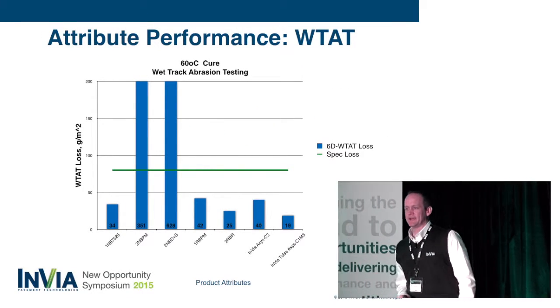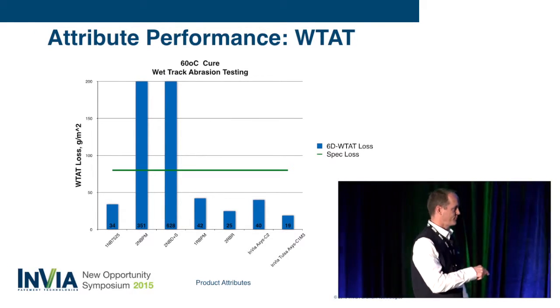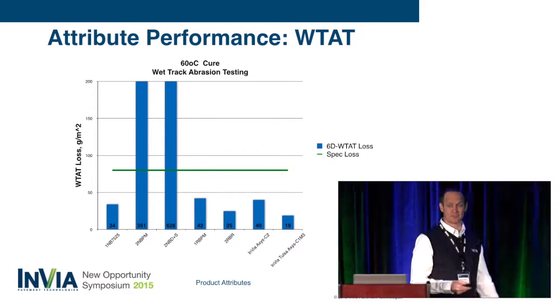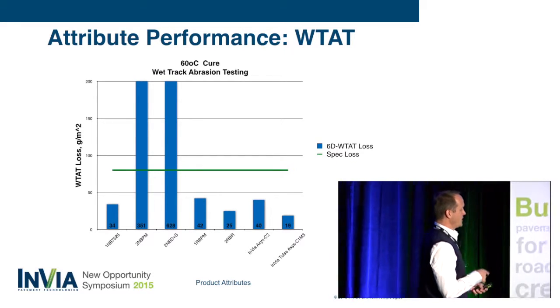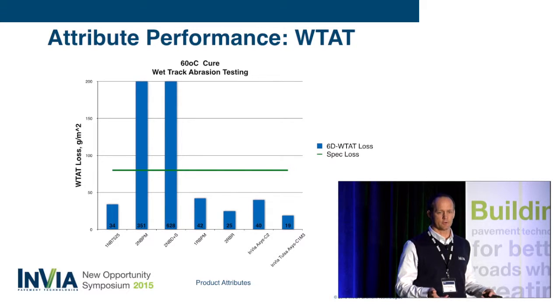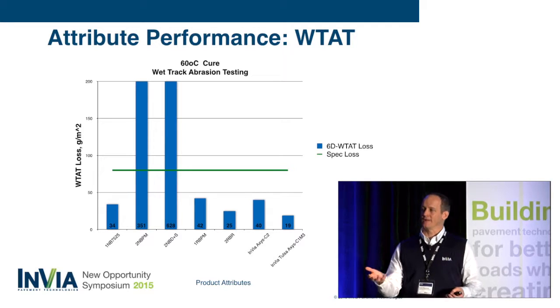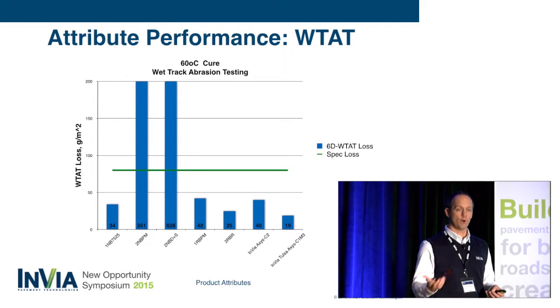I'm not sure if you guys paid attention to the second best performer in that dry time, but I thought I'd go ahead and share with you the wet track because that's our durability surrogate. If you want to dry fast, you can just start with a sealer that has less water. You can put a lot more solids. The thing about solids, right, anyone who's been in the business long enough, solids typically cost more than the water.